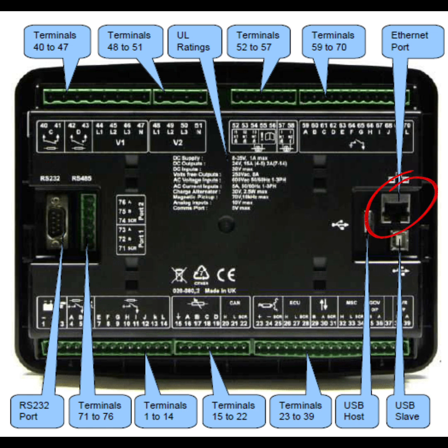And if you need to connect from a laptop to this controller, this Ethernet point is for connectivity, and you will connect your Ethernet wire here. On the right side, near the Ethernet port, another port is USB. You can use this wire for software connectivity. And here is one another USB port. And on the left side there are two ports, one RS232 and one RS485.